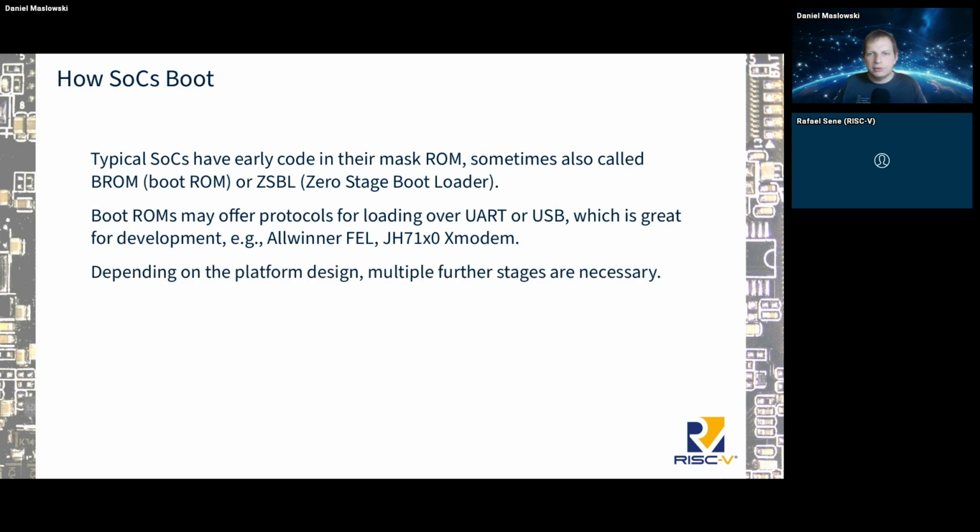And also other vendors I've seen now have something similar. So yeah, depending on the design of the platform, it depends on how you can design your different boot stages after that, right? So yeah, it's really use case specific. So if you look at the code in U-Boot, for example, there are some platform specific parts, and then at some point there is a U-Boot generic part where you have the part you can actually interact with, and that would load your final operating system and so on. And in a similar fashion, it also works like that in Oreboot, right?